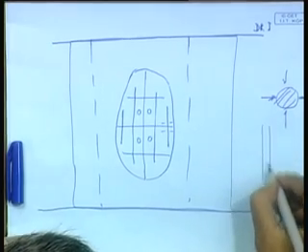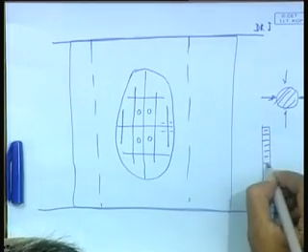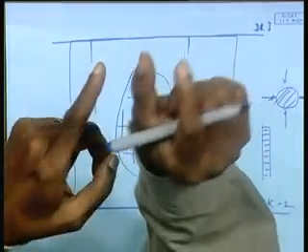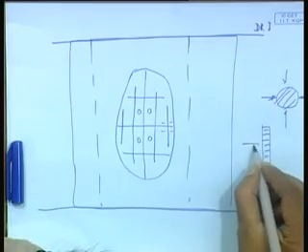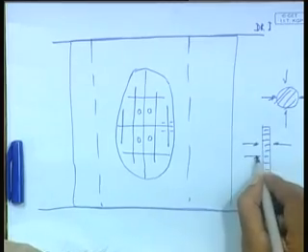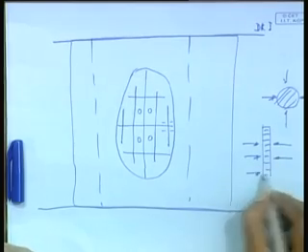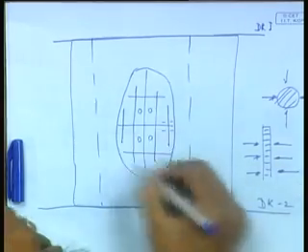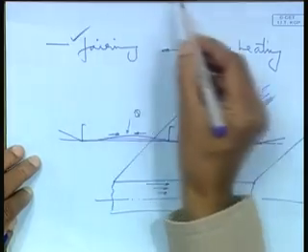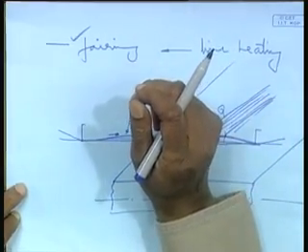When there is a longitudinal heating, this is a heating line. Heating line means it will not be a line, it will be a wide zone depending on the heating torch, say a zone of 10 millimeter. So here the predominant shrinkage is along this. So this is a combination of heating lines, both vertical, horizontal, and spot. That is what is called fairing. This would be one way of combating or mitigating, I would say, weld deformations.